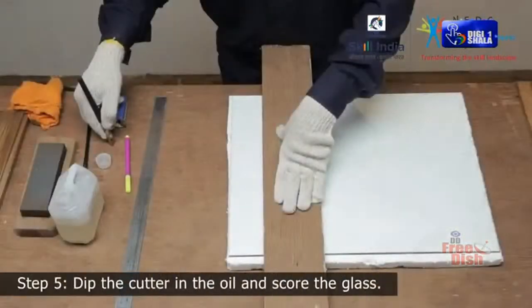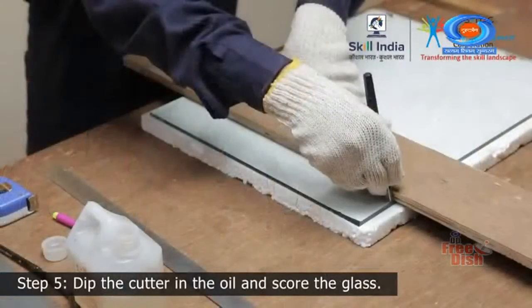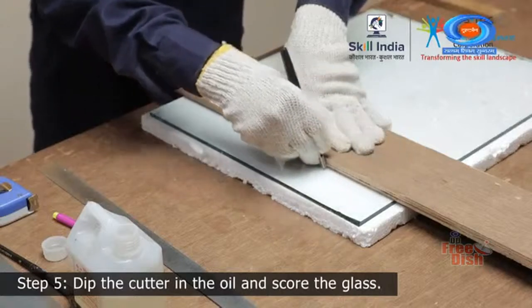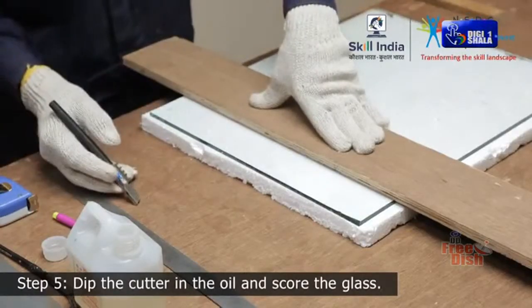Step 5. Dip the cutter in the cutting oil and grasp it like a pencil. Use the straight edge as a guide and score the glass in one even sweeping motion. If you score the glass properly, you'll hear a very pleasant sound like ripping silk. If you see little flakes of glass flying into the air or hear a gritty sound, it means that you are pushing too hard or that you did not oil your cutter.